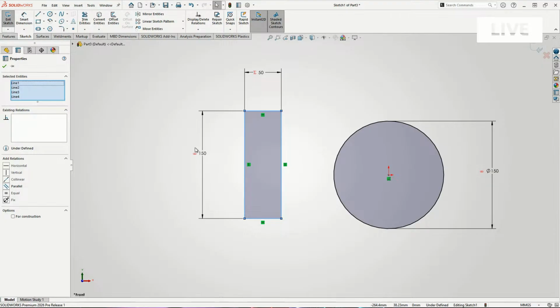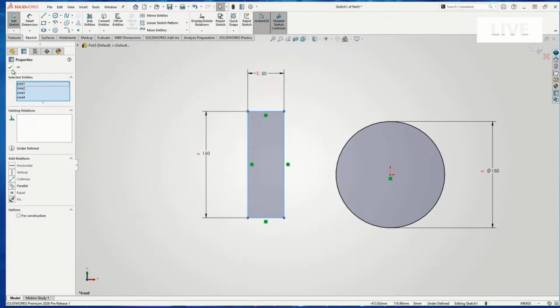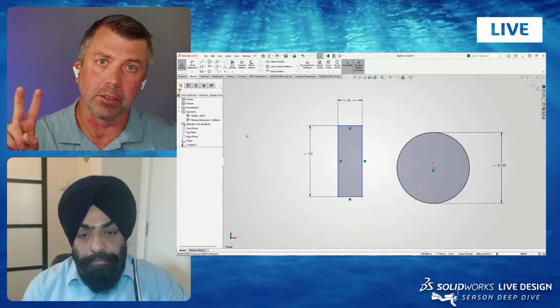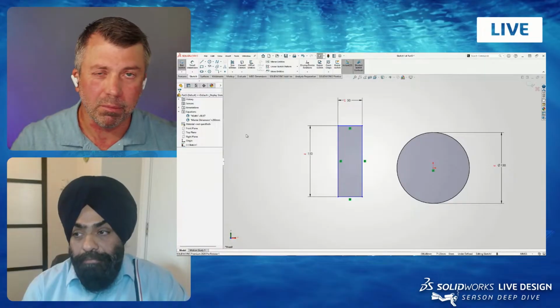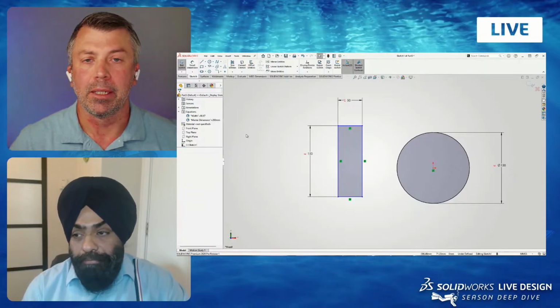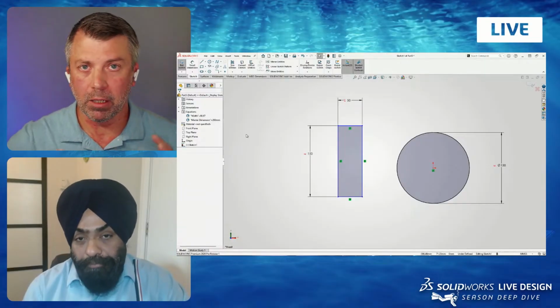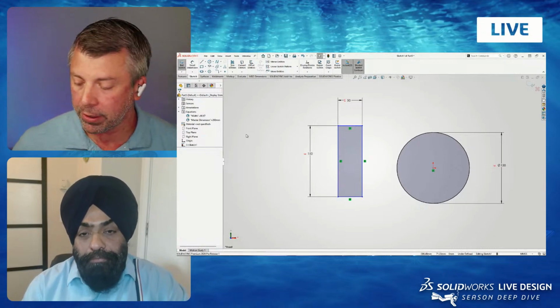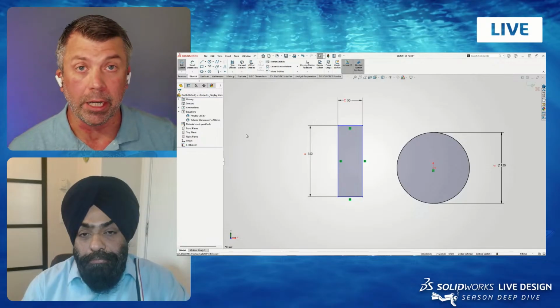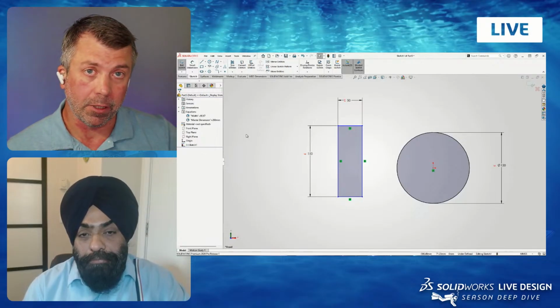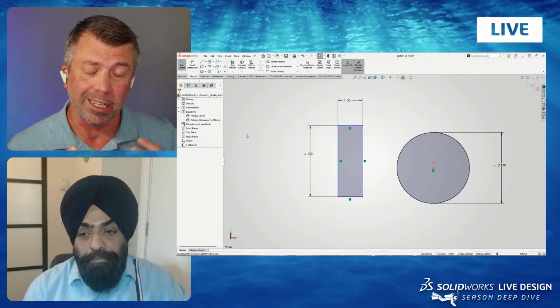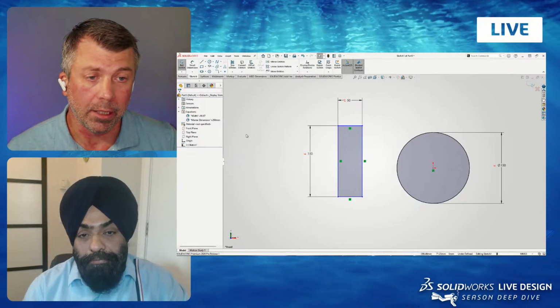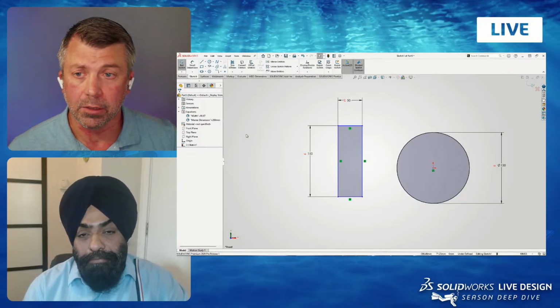So you can get pretty involved with these, and again, I'll show an example here in a little bit. But that's a lot of the basics of those two fundamental things, along with general cleanup and naming dimensions. If you're going to have elaborate master sketches, I do it all the time, especially when you get into configuring those, creating linked variables along with global dimensions and how they can all intertwine. And you can start to drive some pretty good intelligence there.